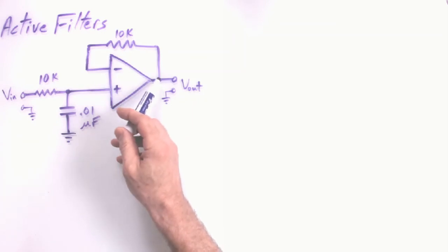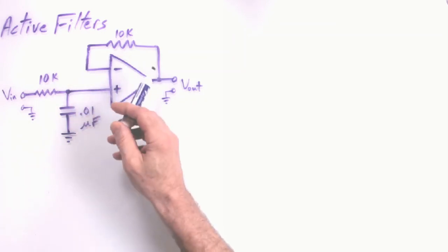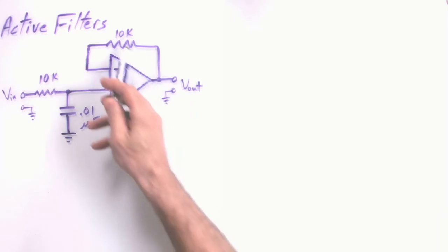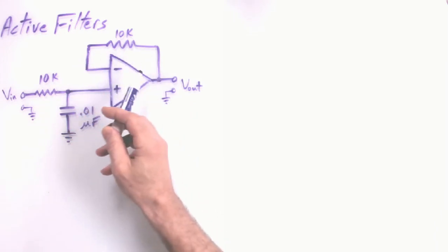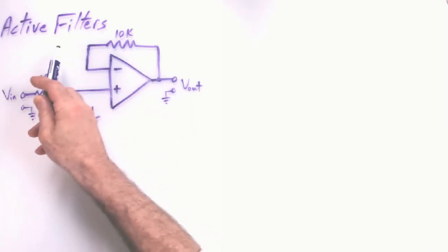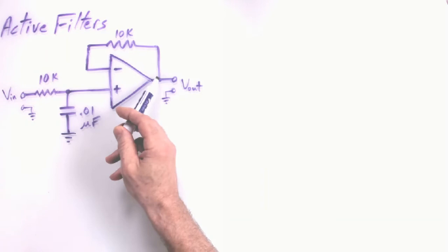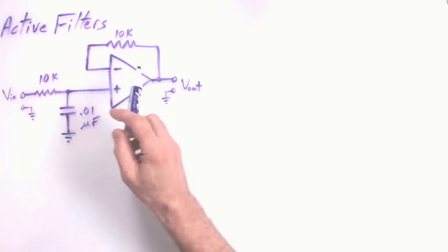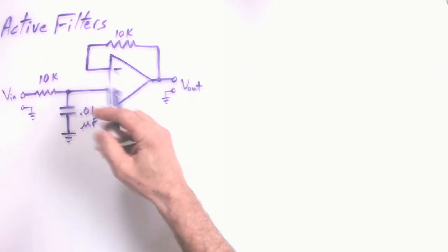If you do a straight connection from here to here, you have a gain of 1, or a buffer. If you use a 10K resistor, you'll also have a gain of 1. You can see there's no voltage division with Ri to reduce the amount that's brought back as far as negative feedback. But I want to bring this up again.